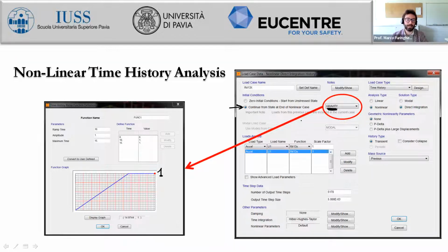This means that with the proper nonlinear behavior of devices, we are accounting for hysteretic damping, which is provided by the isolators. Consequently, the most important amount of damping is already provided by the isolation devices.